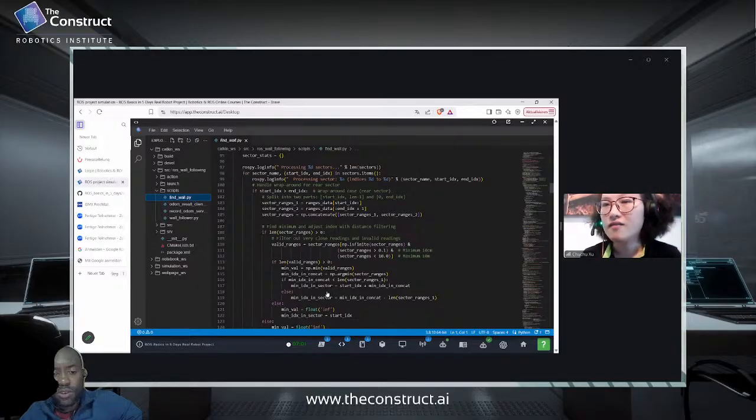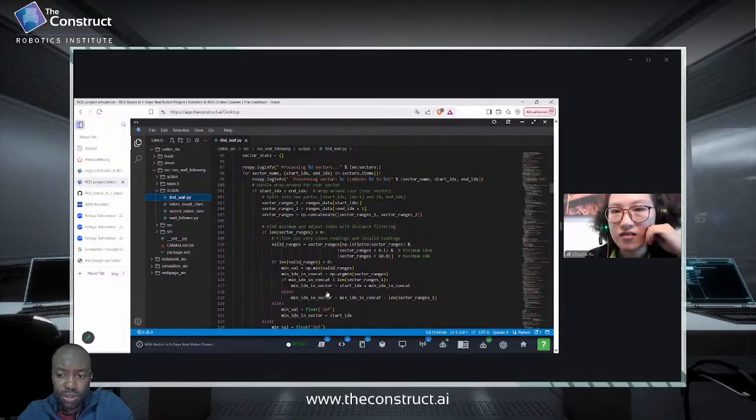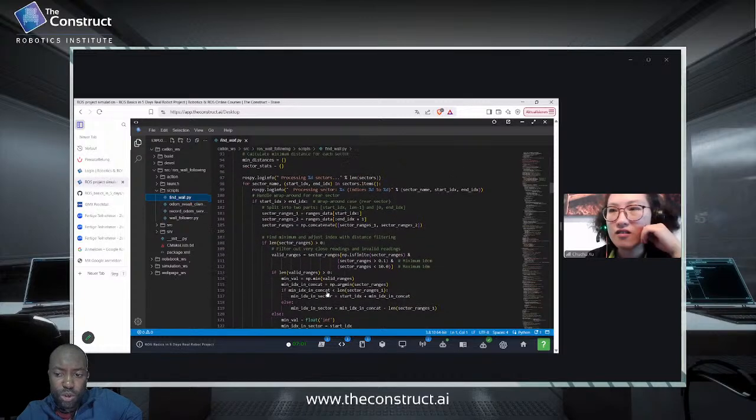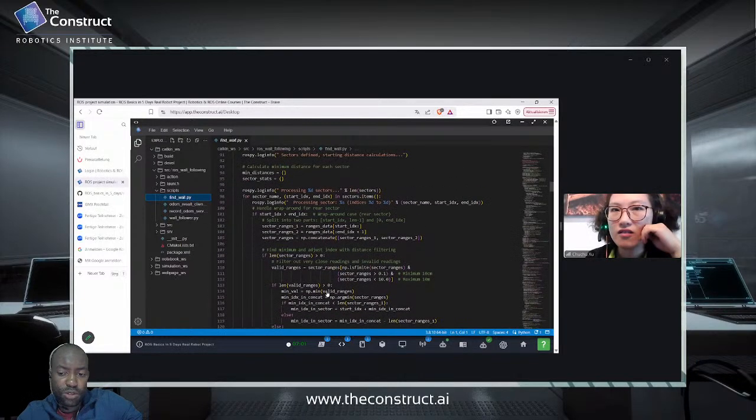Okay, so if you're averaging a 15-degree sector, that is about the space that will be occupied by an obstacle. Why did you choose to average only that small size of ranges data? Because you want to be sure that it's a wall, not an obstacle, right? So what stopped you from taking in a wider range and averaging those laser scan data?